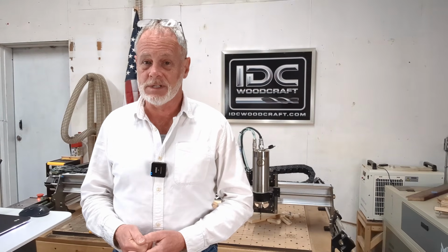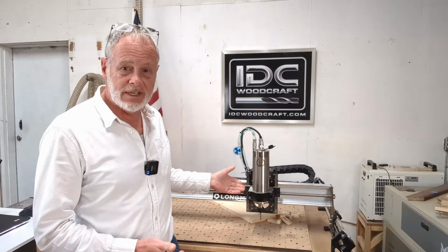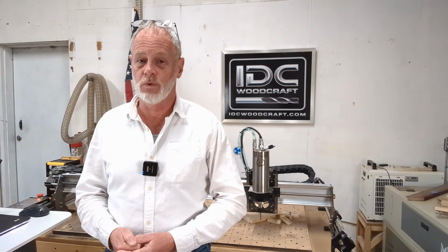When it comes to CNC routing, there are several steps that you have to go through. Number one, you have to design your project. Then number two, generate the tool paths. And then finally, you have to generate something called G-code. G-code is the set of instructions that tells your CNC router where it's supposed to move to and when. When your design is done and you've run the tool paths and generated G-code, you need something to process that G-code. And that's what Gsender is.